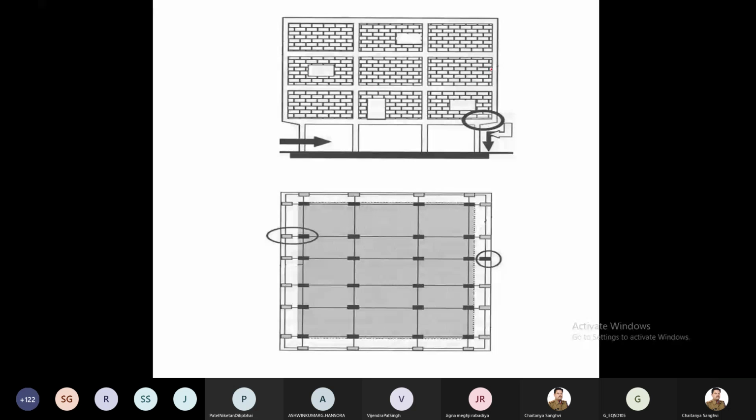Here, what is happening? Generally, in Gujarat, a balcony was permitted before 2001. A 4 feet balcony is provided. So what were the people doing? They were covering the balcony and enlarging their rooms. Actually, their wall or column should come here. Instead of that, they go for this cantilever and then take a column from it, right? A column like this. So what is happening?